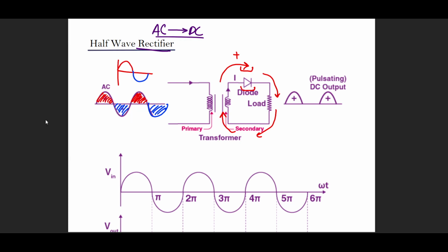When we go towards the negative cycle, we realize that the direction of the current has to be reversed from the initial assumption that we've made. The initial assumption was that the positive current is in this direction, but for the negative current, I will assume it to be in the opposite direction. So the negative current starts from this direction, although positive started from this point. Please be advised, negative current is not flowing. It will not come here and realize that there is a blockage. It will not flow to begin with. We just draw this loop to understand for ourselves that the arrow of the negative direction and the arrow of the diode are not in the same direction.